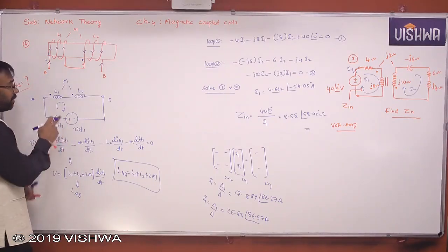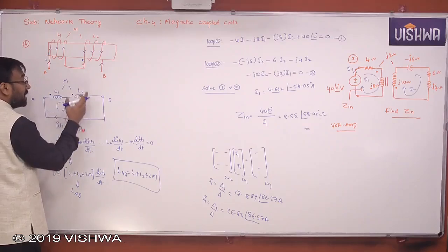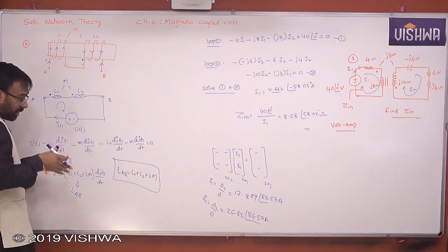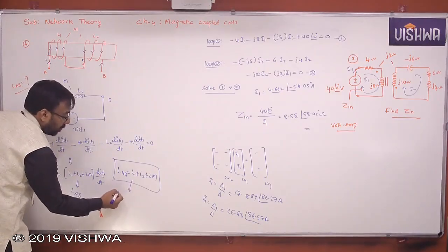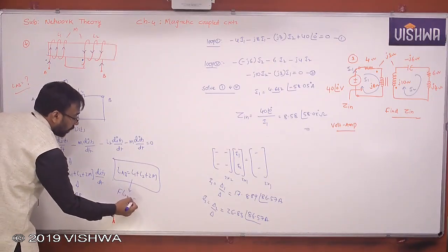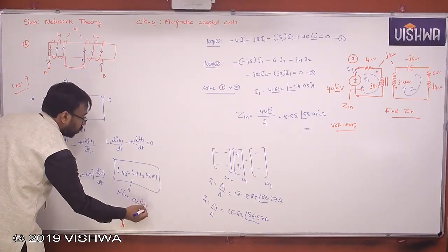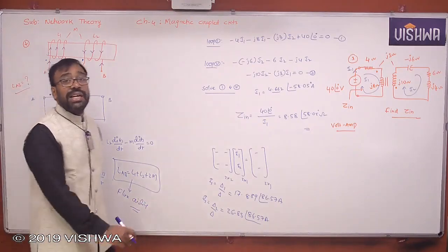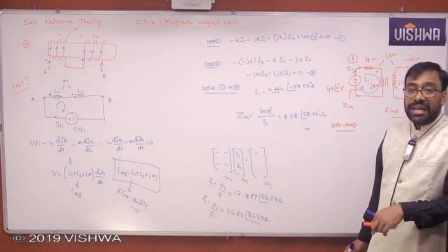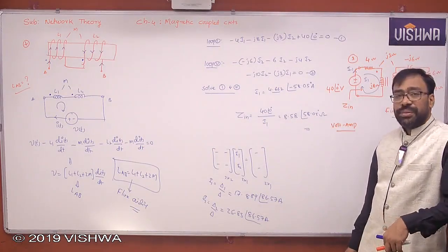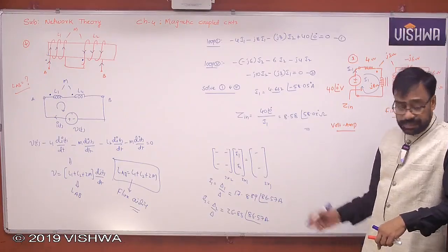Agree all of you? Flux emanated by the primary, flux emanated by the secondary, which is linking with the primary, both are flowing in the same direction. Therefore net flux increased. Therefore this is flux aiding case. So sometimes we will tell two coils are connected in flux aiding case. So what could be the equivalent inductance? L1 plus L2 plus 2M. Understand? Okay. Please note down that.